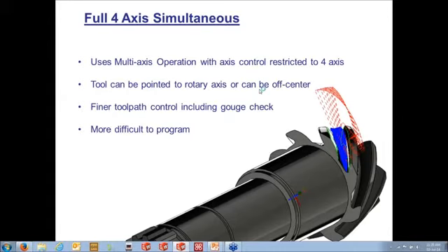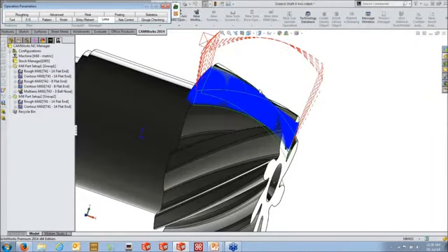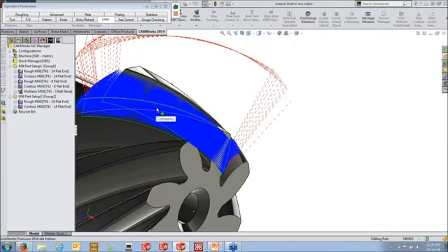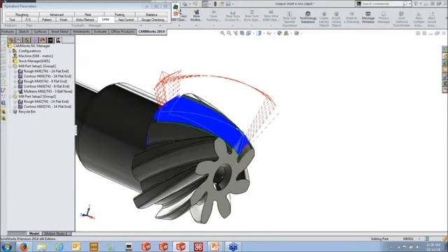So it's just regenerating there. You can see the rapid moves in that image on my PowerPoint between them. It's that setting that drives the tool to pull out when it's finished this particular pass, do a radial move, come back down, and drop back in again, so we don't end up with a direct move between here and here, which would gouge straight through some leftover material.